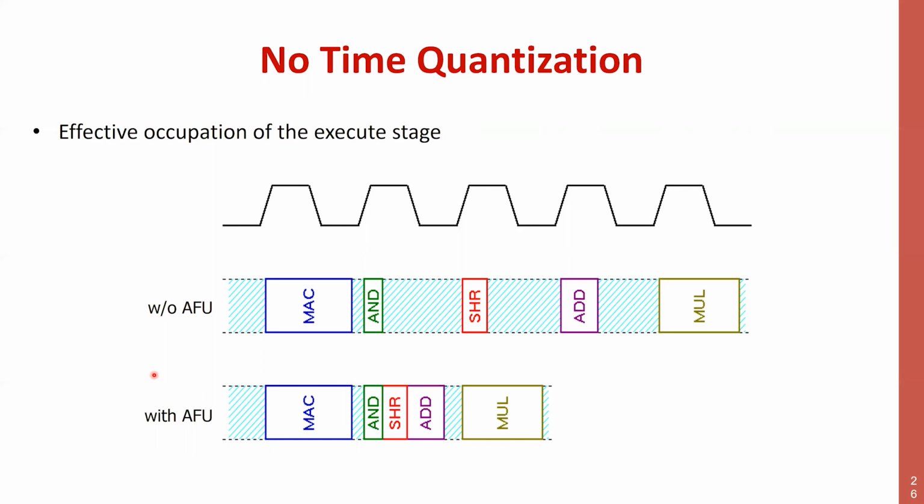Take this only as an example. It doesn't mean that it has to be the same everywhere. But in this case, whoever has done this processor has decided that basically the multiply accumulate and the multiply that are essentially the same length take one cycle. Sort of the relation between cycle and multiplication is this one. Just to be clear, I could have chosen, for instance, to have a clock that is twice as fast and multiplication takes 2 cycles, and instead of going at 1 gigahertz, maybe it will go at 2 gigahertz, right? So this is a choice, it's not important.